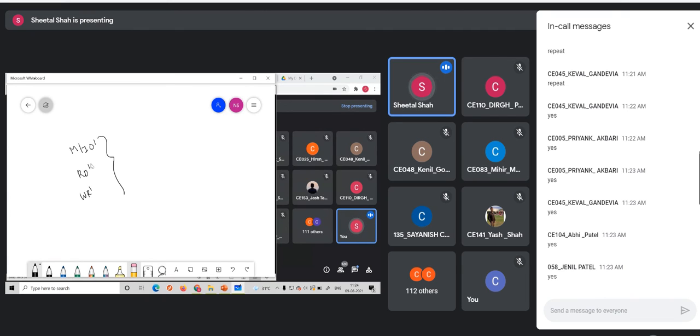So I have to use these to get memory read bar, memory write bar, then IO read bar, as well as IO write bar. We have 3 different pins on the 8086, and using these 3 pins I have to get these four lines. Do you agree to this, all of you?